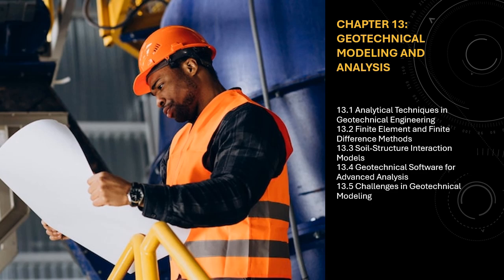13.3.3 Dynamic soil structure interaction. When a structure is subjected to dynamic loads, such as earthquakes, wind, or machine vibrations, dynamic soil structure interaction (DSSI) becomes critical. In DSSI, the dynamic behavior of both the soil and structure is modeled to account for the interaction between them during transient loading conditions.